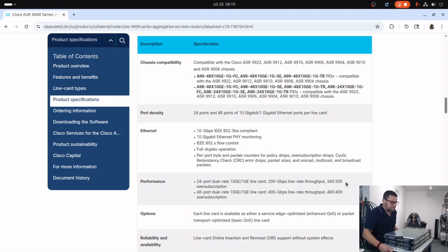Look at that. This is the backplane, and I recommend you check every single one of these connectors. Pay attention to every single pin right here, because sometimes this backplane connector is damaged. If this is damaged, you can damage the chassis, or if the chassis is damaged, you can damage the module.